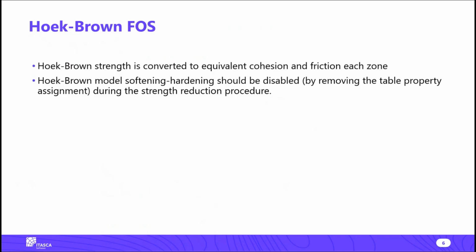For other more sophisticated materials, if you're getting into some of the soils materials like Cam-clay and so on, the factor of safety does not work for those. Right now, it's working for Mohr-Coulomb, Hoek-Brown, and ubiquitous joint.